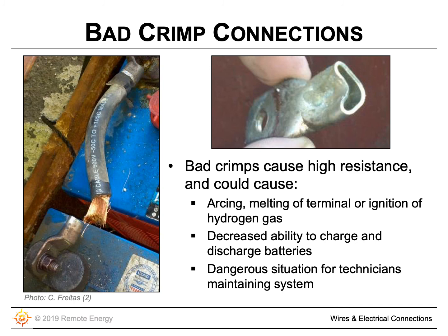And battery crimps are a place where we've seen a lot of failures. This picture on the upper right shows this crimp might have been done with a hammer or a pair of vice grips. And the picture on the left is showing where that crimp just failed. You can see where the wire came right out of there, which causes a really bad connection.